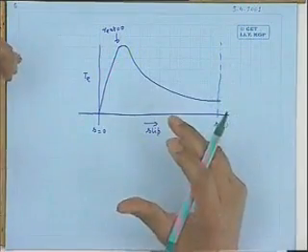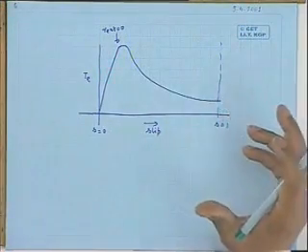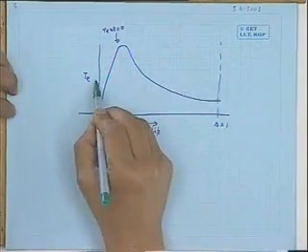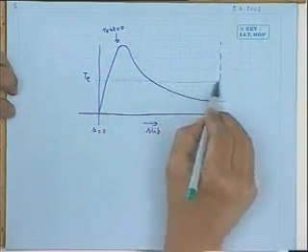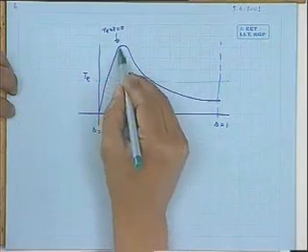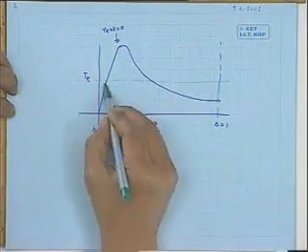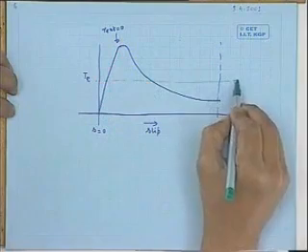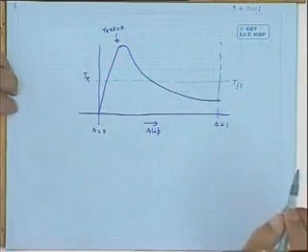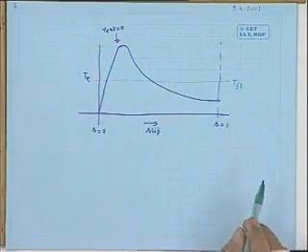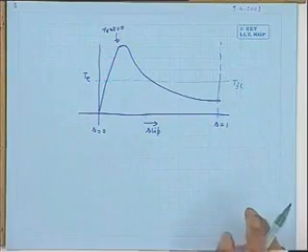Now suppose the machine has to start against full load torque already present on the shaft of the machine, and it is like this. T full load, as I told you, will come midway in this curve about. So suppose this is the T full load torque. And suppose you are going to start the induction motor in the normal way.